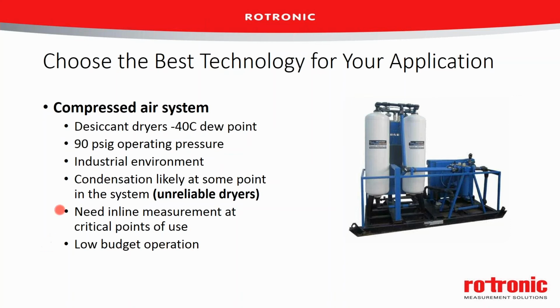So the first thing we want to take into account is the dry conditions. And recalling our technologies that we reviewed, the ones that work well in dry conditions are metal oxide or aluminum oxide, the chilled mirror, and then the capacitive sensor, which has to be specially modified to detect very dry conditions, but there are some on the market. So those are the 3 that can measure dry conditions. We're going to say no to the resistive, no, of course, to the mechanical, and no to the wet bulb.